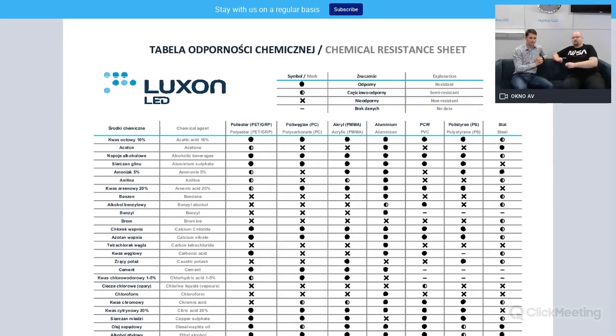Resistance. Okay. Depending on the material, for example, PC is most commonly found to be not resistant to organic fats. If you have mineral fats or mineral oils, then PC is very good with them. But for better chemical resistance to organic fats, such as organic oils, like fat from fat tissue in animals, PMMA and GRP are a better solution because they are not degraded by these materials.